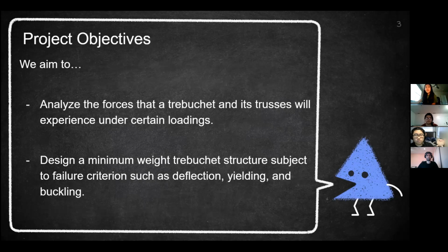This project aims to first analyze the forces experienced by the trebuchet under firing load, and then use that analysis to design a minimum weight trebuchet while taking into account failure criterions such as deflection, yielding, and buckling.